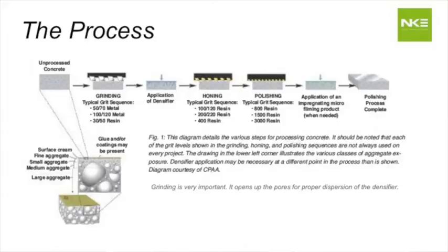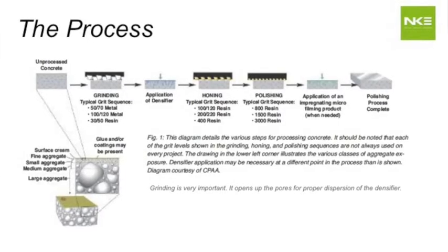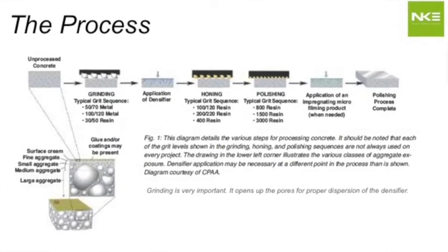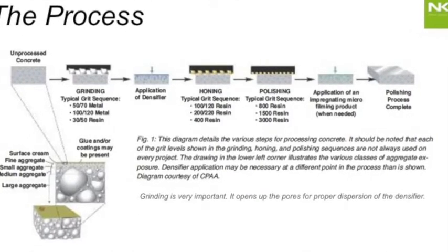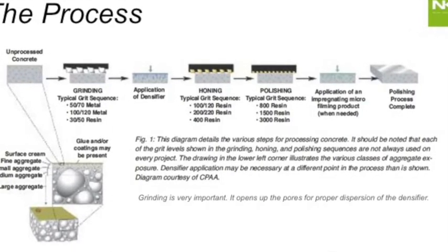So the first thing we need to understand is polished concrete is a process. Okay, the process has four important steps. One is the initial grind, then the right densification, honing and polishing, and finally the sealant application. Polished concrete is not just a finish, not a shine on concrete, but an actual following of these four processes. Based on your final use case, you can change the intensity of each process, but these processes have to be followed for the system to perform.